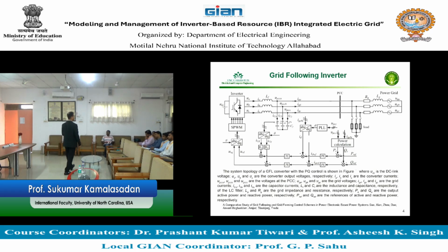Why do you need a controller there? There is a reason for that also. So 59.9, I am getting that angle and I am taking it, right? Is this 59.9 of the electric grid stable? Always 59.9? No. So the electric grid is moving. I am taking from the electric grid, and I have to keep on taking from the electric grid because the electric grid is moving. You see? That's why we need a controller to adjust it. Are you following conceptually what is happening? So that is what we call a PLL. Then you can convert from ABC to DQ, and then you are able to design controllers.